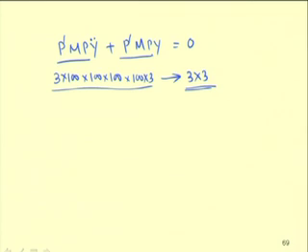One may note that for a multi-degree of freedom system, the free vibration of the system is written as x. It will be the summation of different normal modes. Let the modal vector for the first mode be x1, for the second mode x2, for the third mode x3, and for the n-th mode xn. One can find that these modal vectors correspond to the eigenvectors of the system.